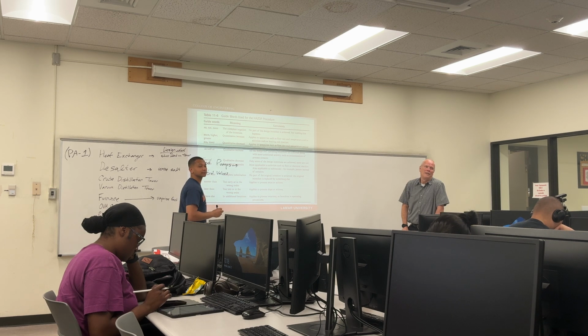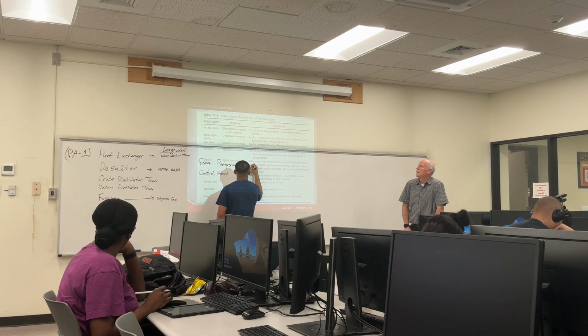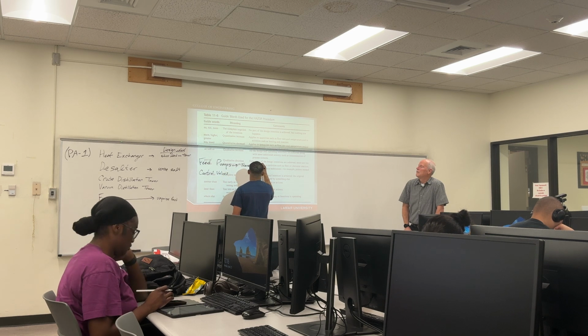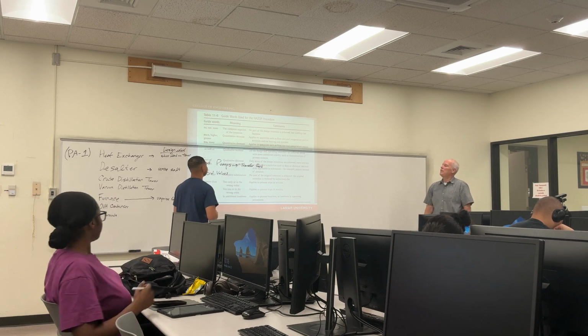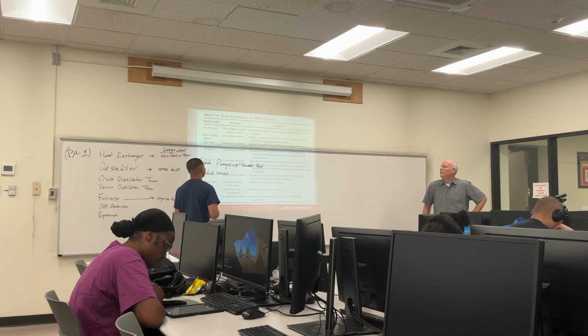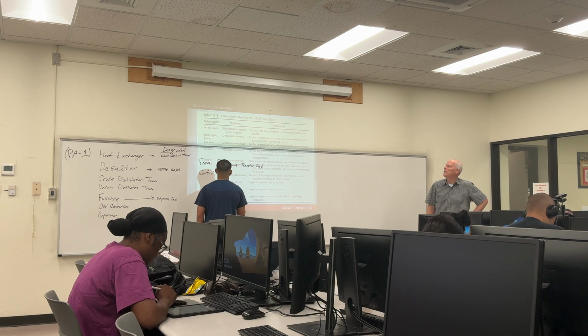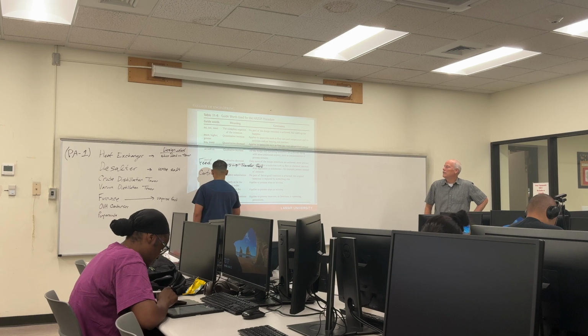Create flow. Transfer the feed. Increase the pressure. And for the feed pumps, is there going to be a control valve associated with that somewhere? You would think so. So draw a pump and a control valve where you're controlling flow. Well, I don't see a control valve yet, but whatever you want to draw a pump as, right?